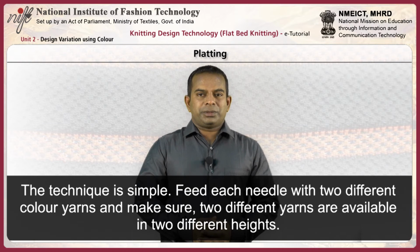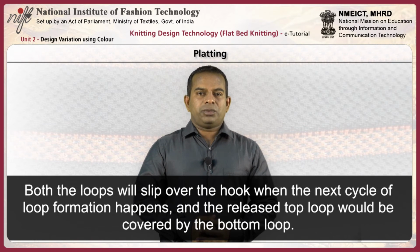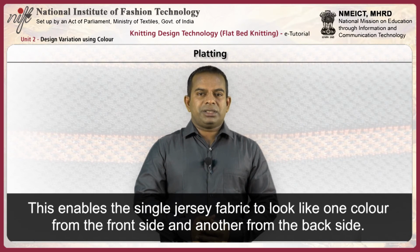The technique is simple. Feed each needle with 2 different colored yarns and make sure the 2 different yarns are available at 2 different heights. This will ensure when the needle comes down, one loop would always be on top side of the hook and the other always just below that. Both the loops will slip over the hook when the next cycle of loop formation happens, and the released top loop would be covered by the bottom loop. This ensures single jersey fabric looks like one color from one side and another color from the other side.